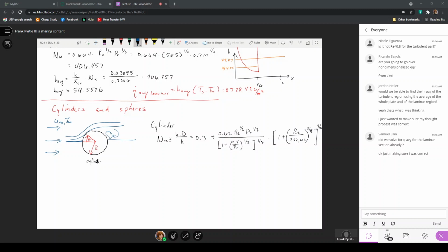That is for what we consider turbulent flow conditions, and you basically end up with a much larger pressure drop from the front to back of the cylinder, but you get much higher heat transfer coefficients on the backside due to the rotation of the fluid that increases the interaction of the fluid molecules with the solid surface.